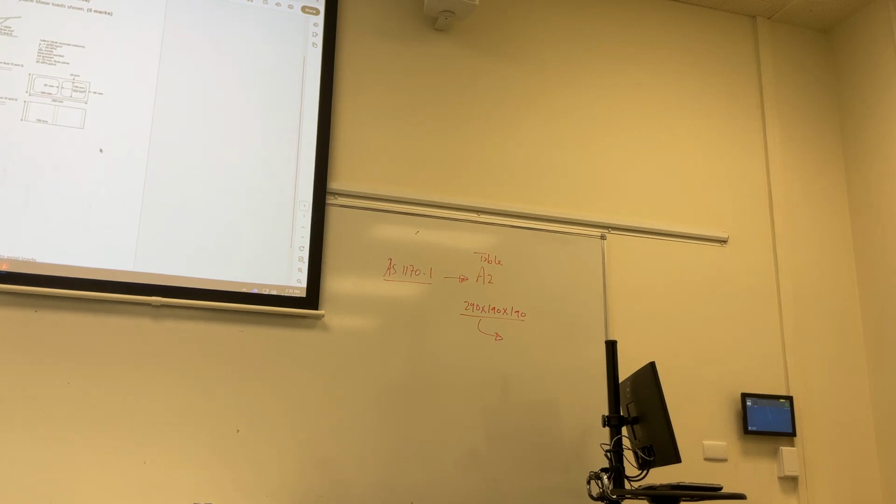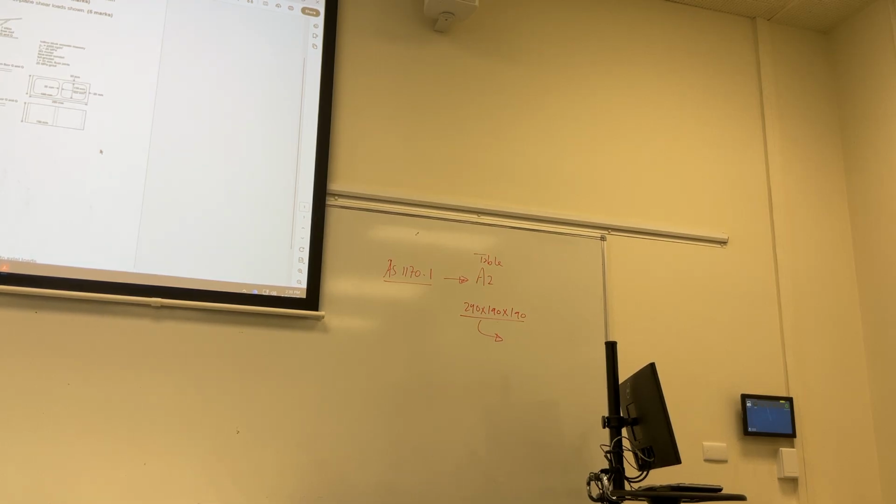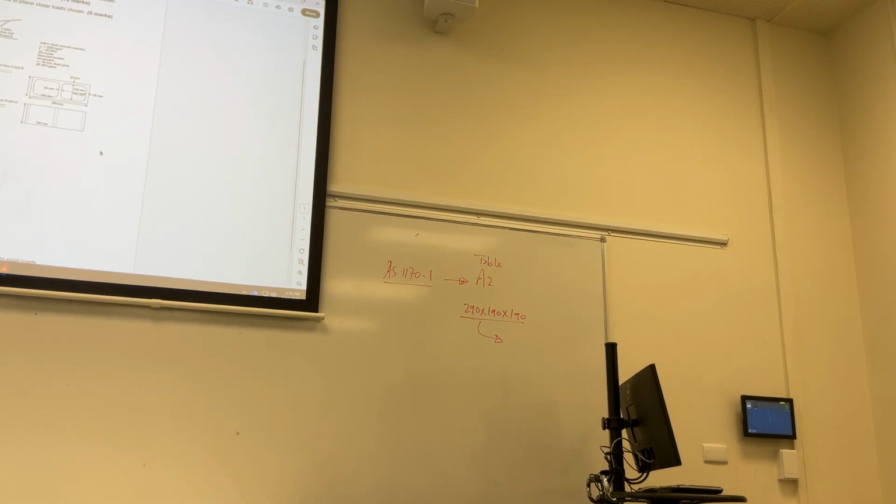Okay, this 2.1 is kilonewton per meter squared, kilopascal. You need to divide by the thickness to get it as kilonewton per cubic meter. You will find it around 10 or 11. If you remember, we calculated it as 11 kilonewton per cubic meter. So this block's density is less than 2,200 kilogram per cubic meter. So Kc should be 1.2, but it will not affect your result. If you did it at 1.4, it's okay as well. So this should be 1.2.